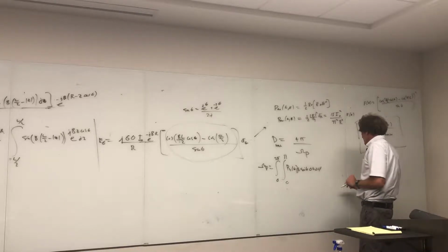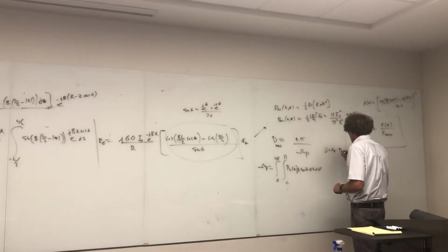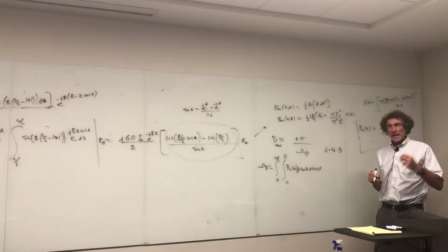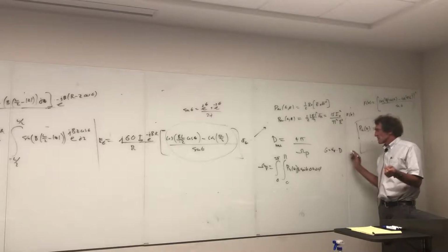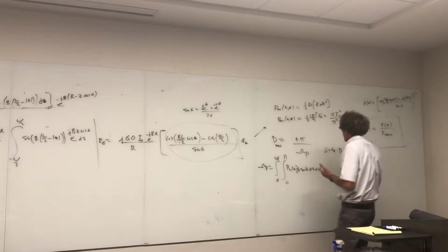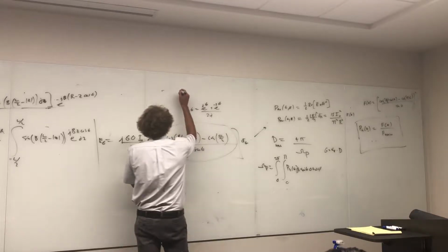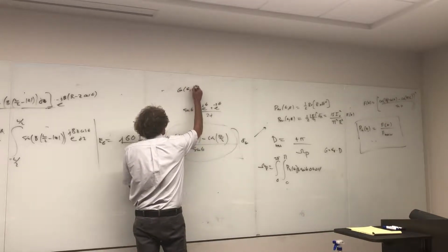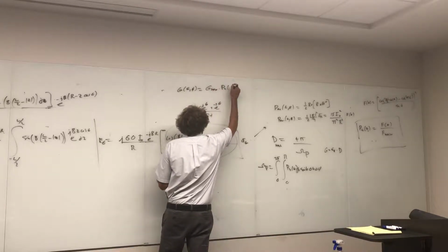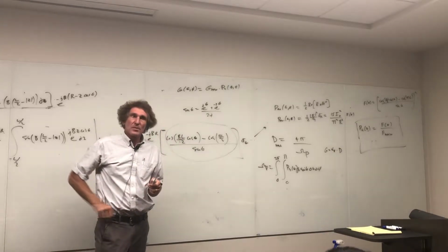And then we'd get the gain, if we needed it, by finding the antenna efficiency times the directivity. And that's the maximum gain. Do you all agree with that, class? The gain in general is the maximum gain times the normalized power pattern. I want to say that several times. So if I want gain in general, I always run out of board, but I'll put it here. In general, gain as a function of theta and phi is going to be the maximum gain times the normalized power density. And that's important. And that's used all the time.